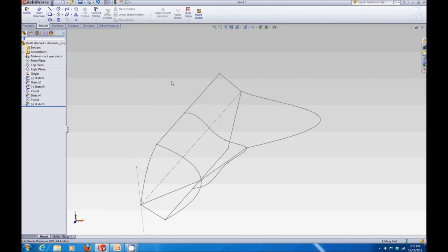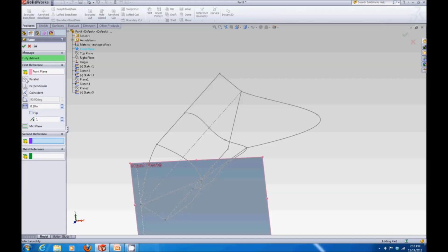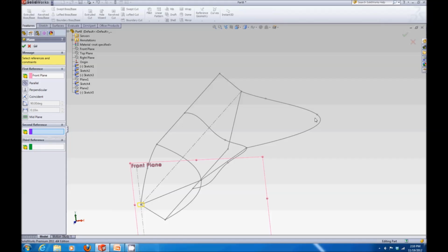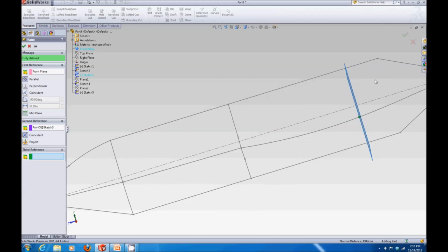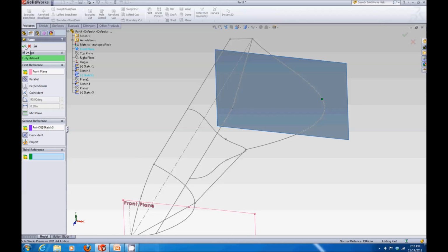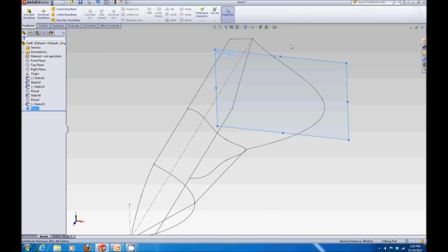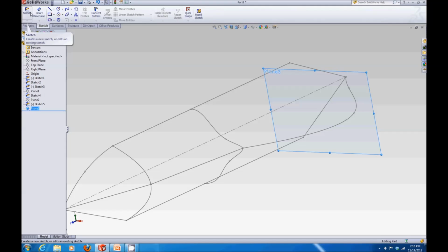And now we can do a third one on this last point over here. So we need to add another plane. We always want it parallel to the front plane because the front plane won't ever change. The second point will be that point right here. By making it that point, it's not quite where the fuselage ends, but if that point changes, then it'll also change our right plane, which is great for later on if things change. So we'll want to make a sketch on that plane.